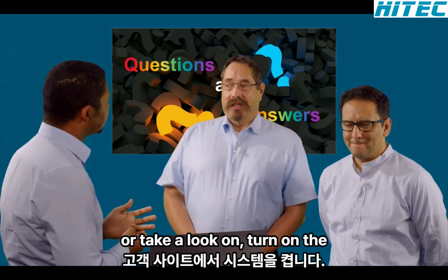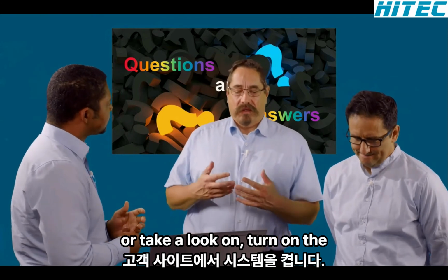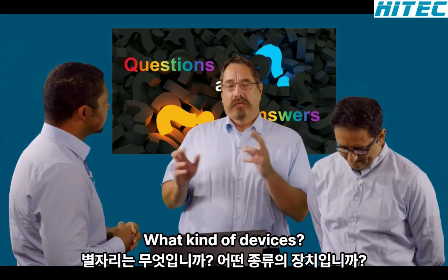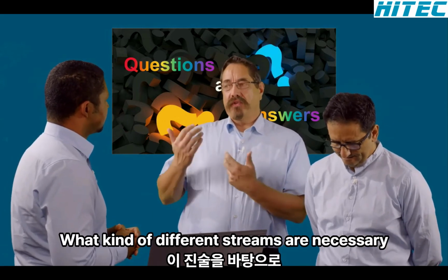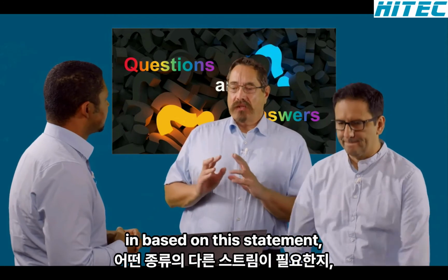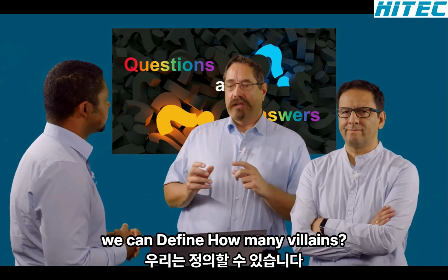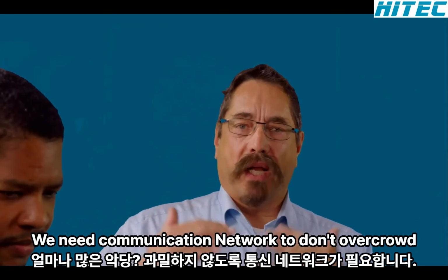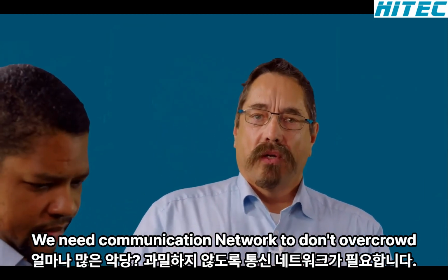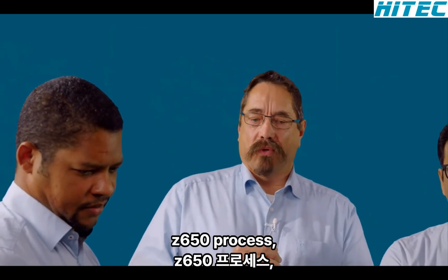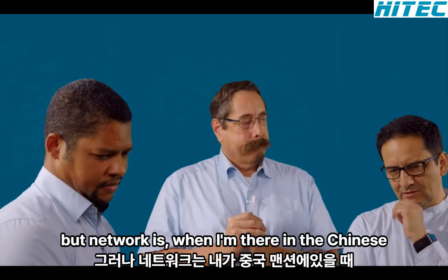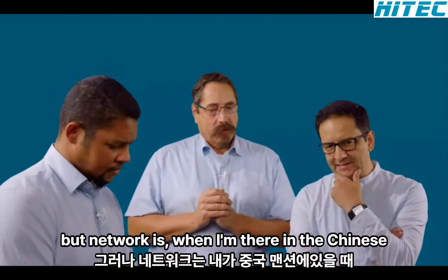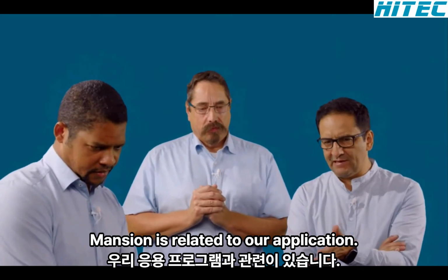Yeah, the answer is it depends, because we have to really take a look at the system on the customer side. What is planned? What is the constellation? What kind of devices, what kind of different streams are necessary? Based on this, we can define how many VLANs we need. At the end, we have to find a good balance in the communication network to not overcrowd the 61850 process bus network. There is one topic that the colleague in the chat mentioned, related to whether we have a VLAN for Goose.